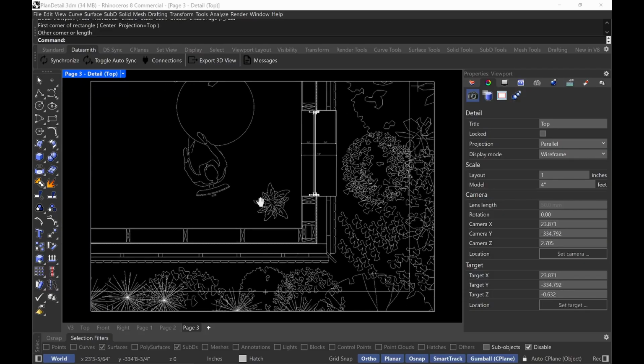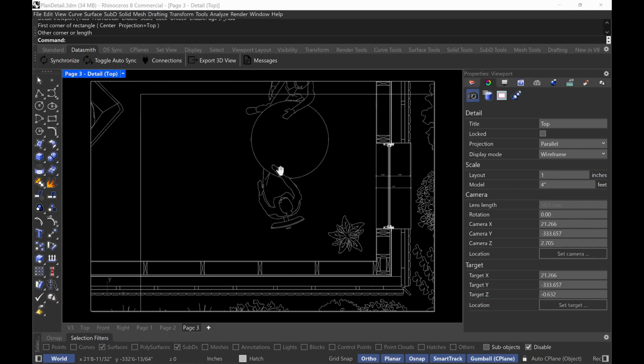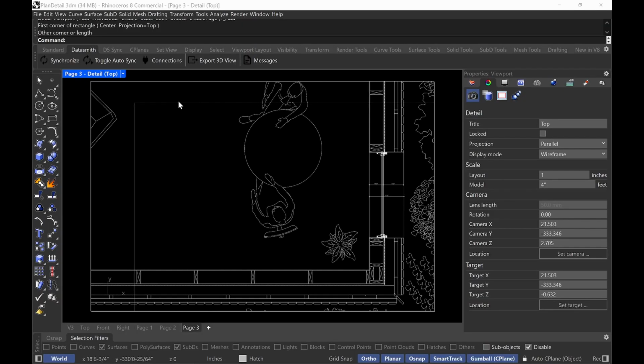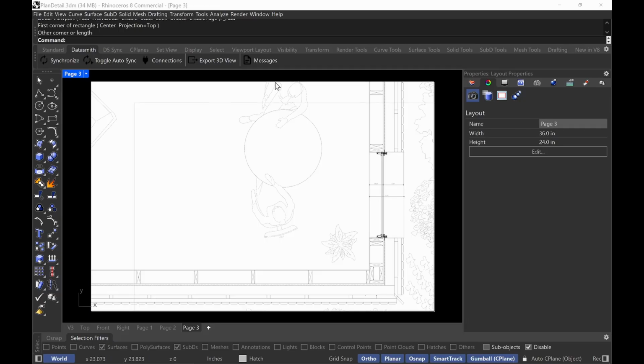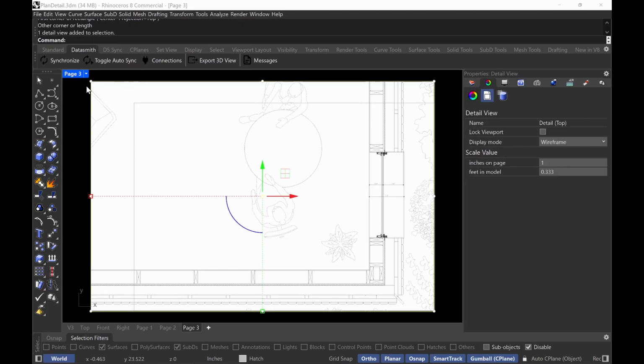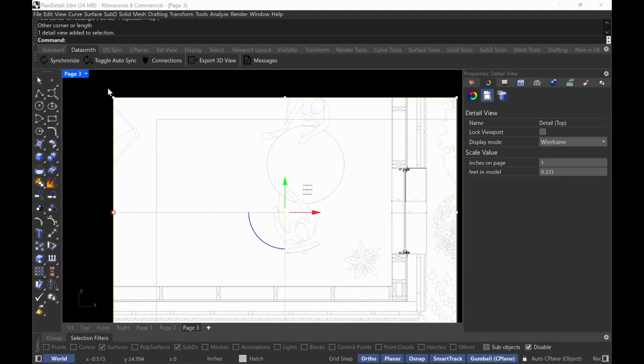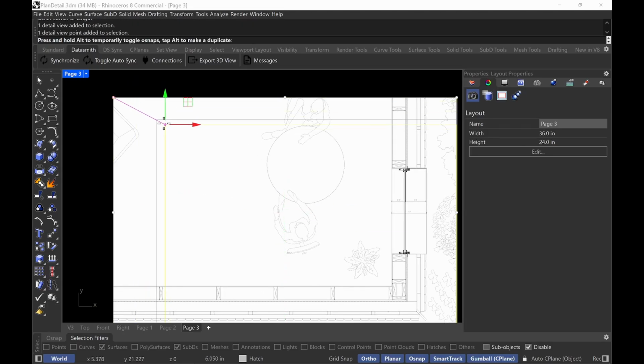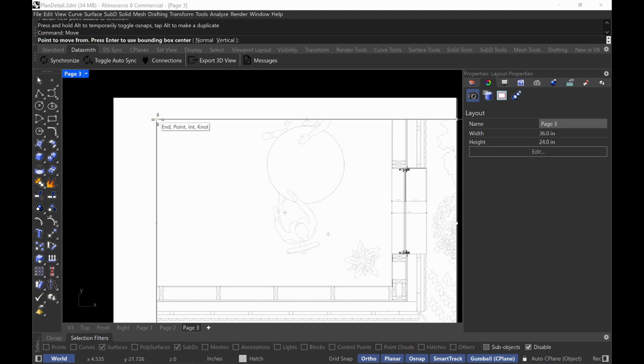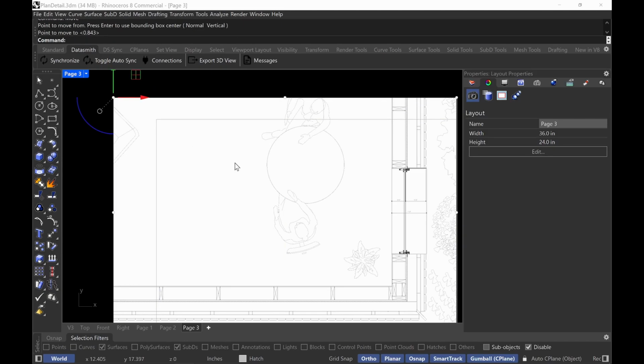So what I'll do is, let me find an easy point. I'll use this top left corner. This is why I have this, so I can use it as a reference to perfectly line up with my drawing. That's why. Okay? So I can click outside here. I'm going to click on my little detail, the detail viewport rectangle, and you can move the corner. So I can go here, take the gumball, move it to this corner right there, type in move this to that corner up there.